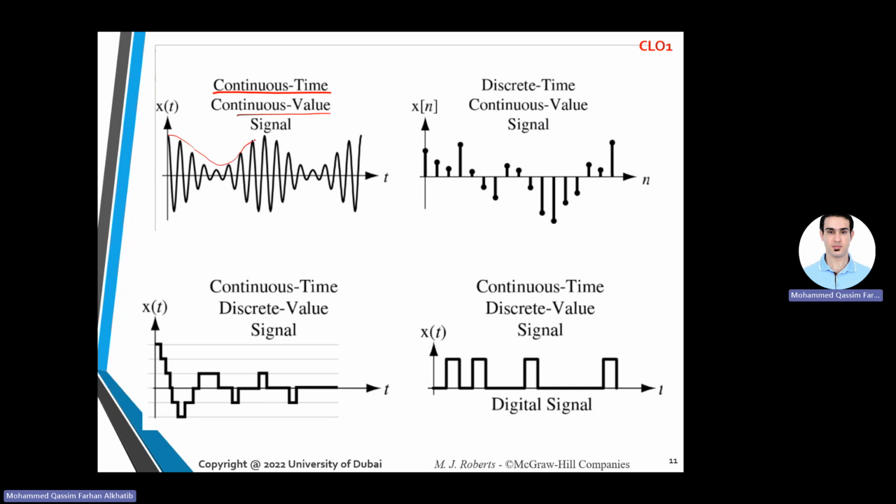That's a modulation signal, by the way. So you have what we call an envelope, and you have the signal inside, but there are no discontinuities anywhere. So that's a continuous time signal. This one here is discrete in time. So that's a discrete time signal, but you can have any value in here. I'm not restricted by certain levels at the y-axis. So it's discrete in time, so I don't have any value here or there. So it's discrete in time, and in value, it is continuous.